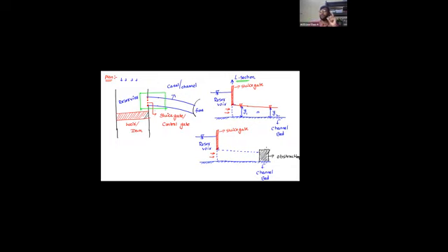Now what I am representing here is, you see, this is an obstruction, the flow is happening, and if that flow hits the obstruction, immediately the water level will rise or not? Immediately the water level will rise. Sir, what is happening over here is, when the flow hits the obstruction, the velocity of flow will decrease. Kinetic energy will decrease. And that kinetic energy will convert to potential energy.